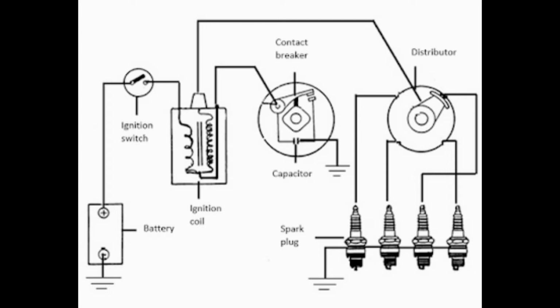How does it do this? The ballast resistor is made of iron wire, and iron wire has a property that its electrical resistance increases rapidly with a small increase in temperature. If the current from the primary winding flows continuously, the temperature of the ballast resistor increases, and this increases the electrical resistance and reduces the flow of electric current through the primary winding. The reduction of current by the ballast resistor prevents the overheating of the primary winding.